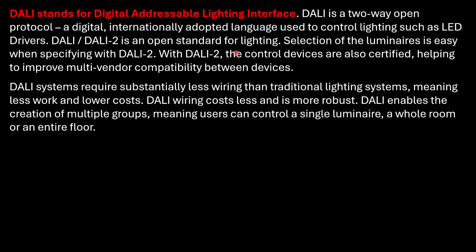With DALI 2, the control devices are also certified, helping to improve multi-vendor capability between devices. DALI systems require substantially less wiring than traditional lighting systems, meaning less work and lower cost. DALI wiring costs less and is more robust. DALI enables the creation of multiple groups, meaning users can control a single luminaire, a whole room or an entire floor.